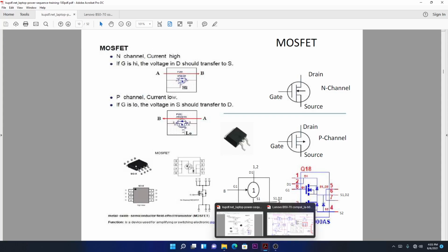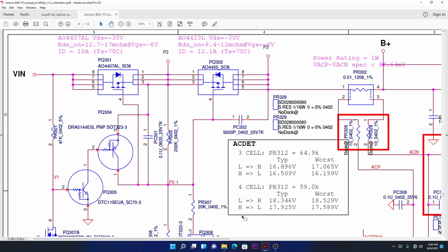For example, on a charging port, I don't see a reason why you'll want to put an N channel MOSFET. For what reason? Because there will be nothing turning on and off, nothing is switching here. There's no PWM here. Even if you put one MOSFET, it's fine.